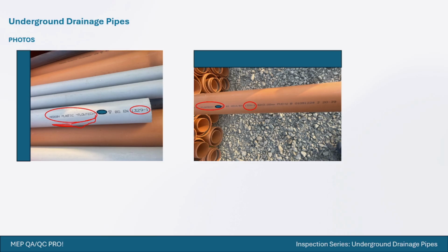You need to check that your first checkpoint is the brand, then the standard. Here we have hidden something for some reason. Then you need to see which country your pipe is coming from, the country name. For this specific area it is a local company, so we have hidden its name, whether India, UAE, or Saudi.